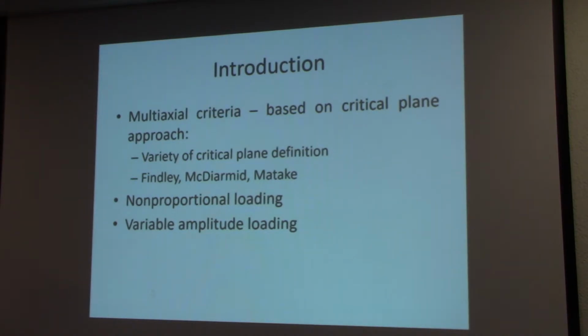As my main interest will be in the multiaxial criteria and the definition of the critical plane, we will be talking about non-proportional loading in the way that I will do the simulation when I load the component with a very simple loading sequence, which is composed of three proportional loadings, but each of them has a different orientation of principal axis, so the whole sequence acts as non-proportional.